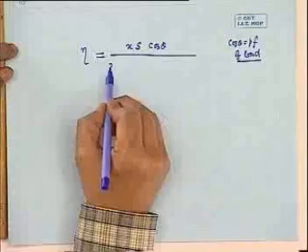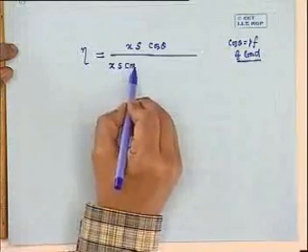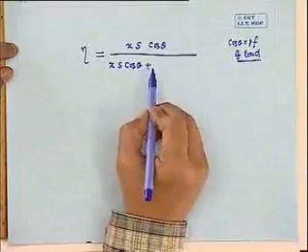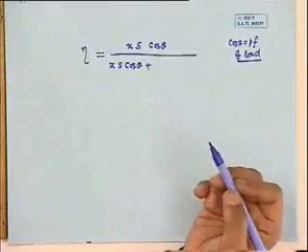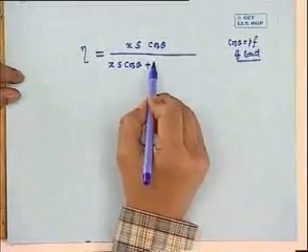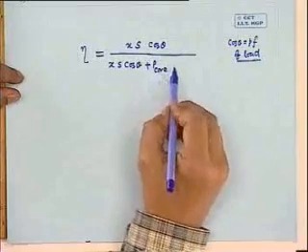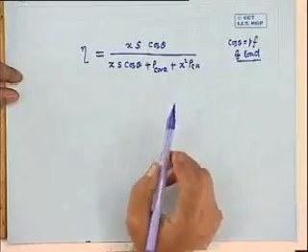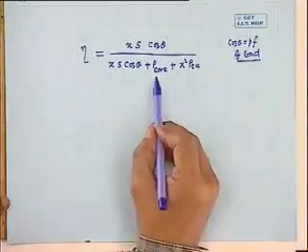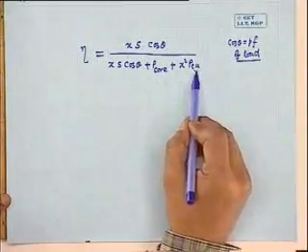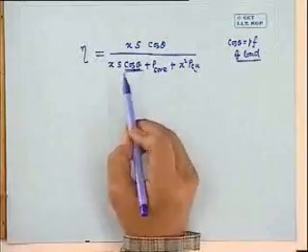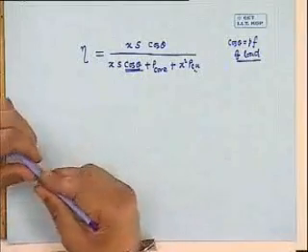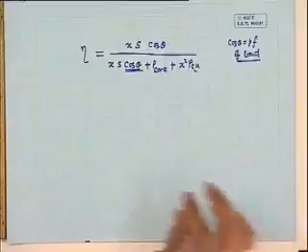Kilowatt you have to express. Output divided by input. So input will be this output plus what? Losses. What are the losses? P core. It does not change. And plus x squared PCU, where you should remember P core is constant, PCU is defined at a particular load, and of course cos theta is changing with load power factor.